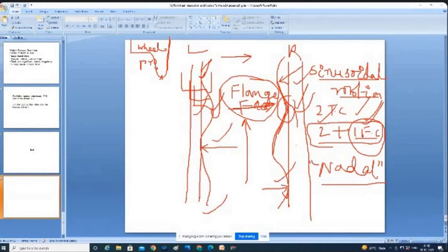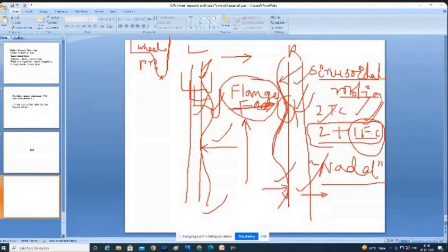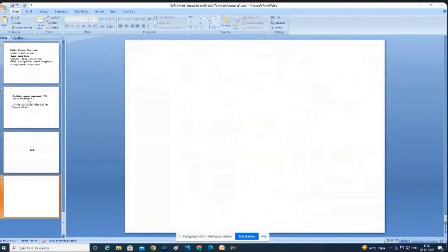Yes. Whenever there is one additional flange contact, that is whenever on one side the play is 0, at that time only it will hit. Okay. So similarly, after a little movement, it will hit left side, then right side, then left side, then right side. It will keep on moving like this. Suppose at that time, if the track is weak, while hitting, what will happen? It will move this side. That means the gap of 1676 mm will increase.